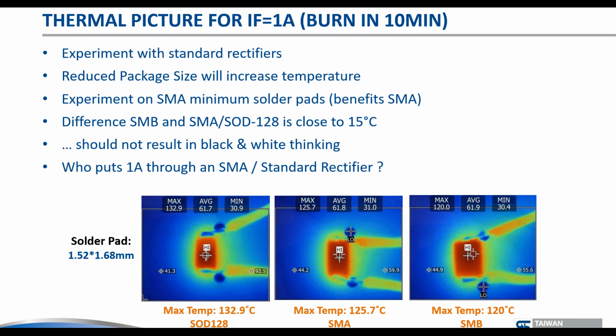Definitely. If you take half a watt, people don't want their design to become 10 or 15 degrees hotter. Now, if I use an application where I dissipate 100 milliwatt, which is not unreasonable for these packages, if you just need the big surge and put 100 milliamp through them, then you're talking about differences of 3 or 4 Kelvin per watt, or 3 or 4 centigrade.